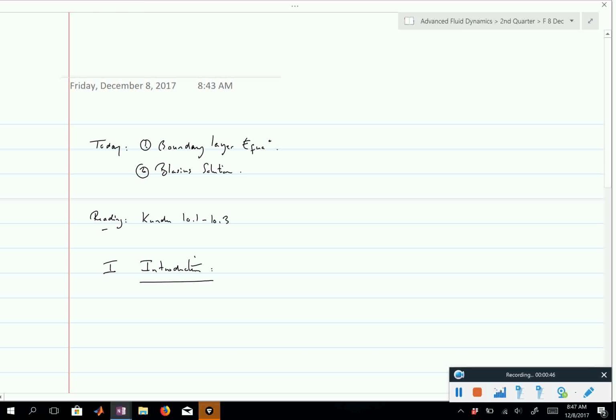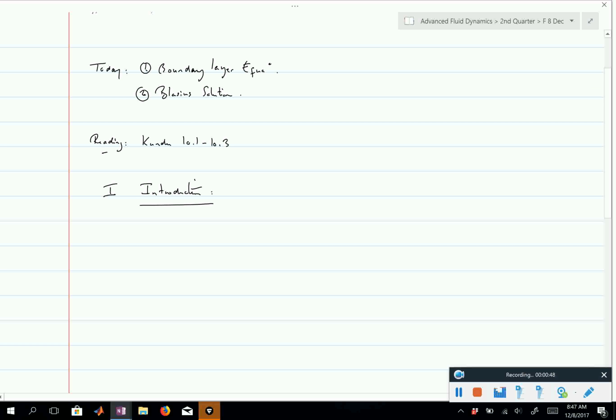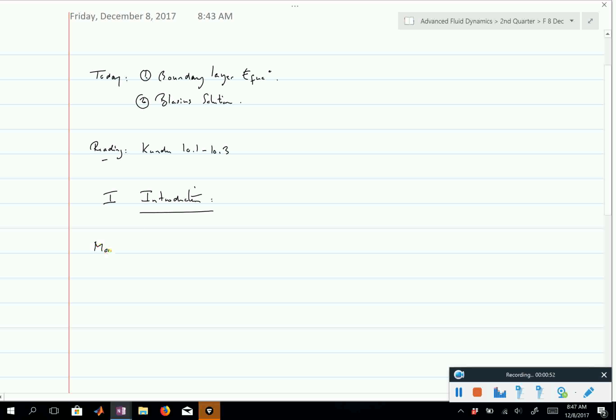And so we'll just start with reminding ourselves of the momentum equation. So here is our momentum equation. The inertial term on the left-hand side, which comes just from the mass times acceleration term for a continuum. So rho partial u partial t plus u grad u.